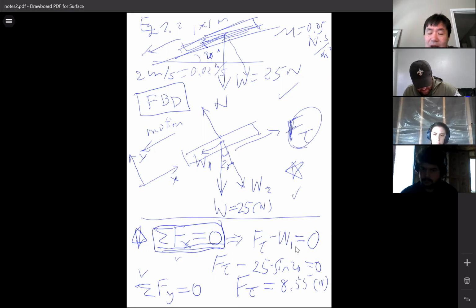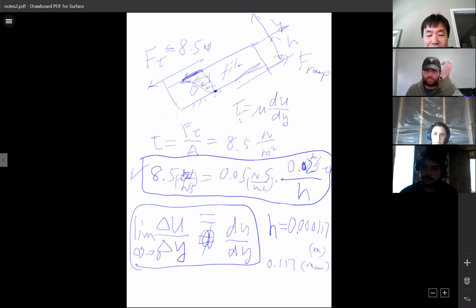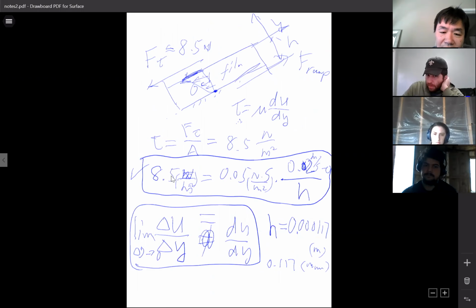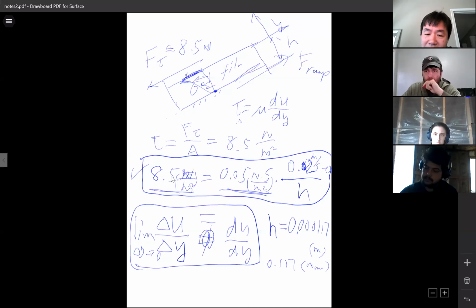No, right? It doesn't matter. This equation, 8.5, is to ensure a constant speed going down. It doesn't matter what the constant speed value is. So the only thing that matters here is the h, right? So in this equation, 8.5 doesn't change whether you increase or decrease the speed. Viscosity won't change either. The only thing that could change if you increase the speed is the last term.